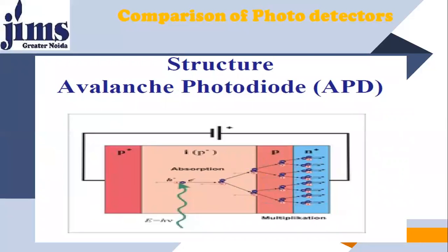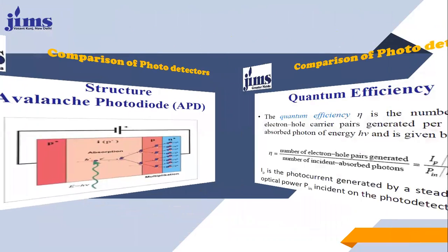By high reverse biasing, with the intrinsic layer in the middle, the absorption of one photon creates a free electron, and this highly accelerated electron creates two more electrons, two create four, four create eight, and this is the multiplication. Because of this multiplication, you get a huge amount of current. So the current is amplified internally, and this is the basic concept involved in the avalanche photodiode.